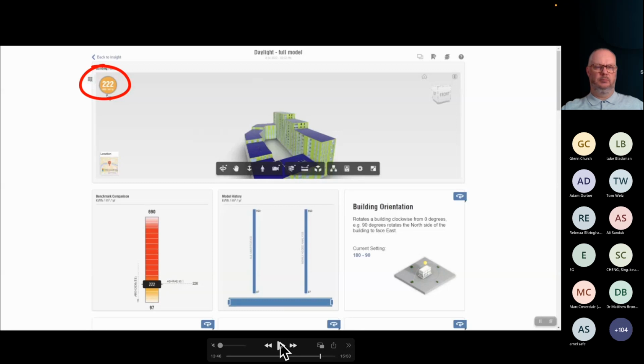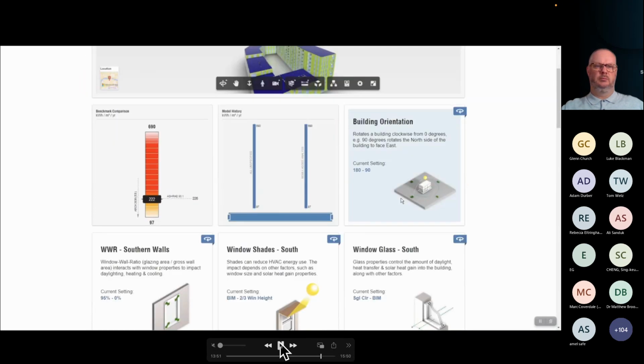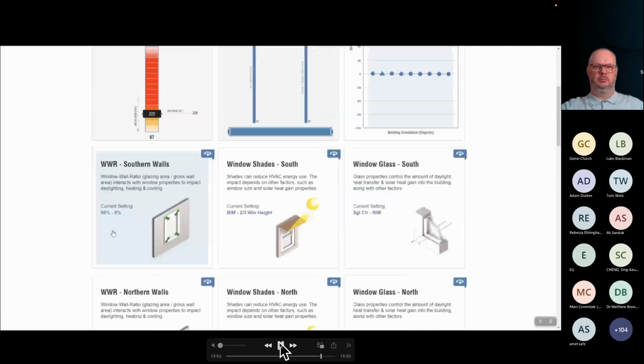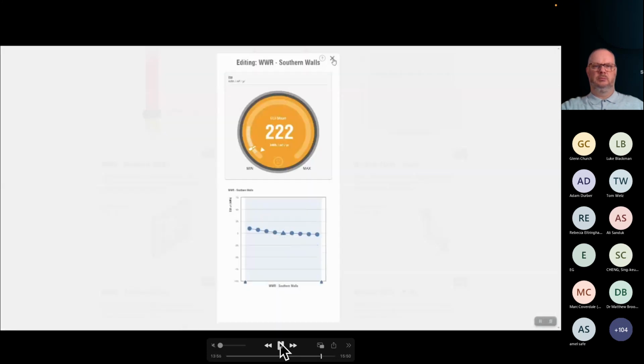What can you do as well? Well, because we now have a full BIM model with the right openings and build-ups, we can just send this into Insight Energy and run a new analysis there, and you can go way more granular in order to understand how you can optimize consumption, right? You can do things like change the window to wall ratio, but you can also study window shading, for example towards south. What kind of solution can you use over there?